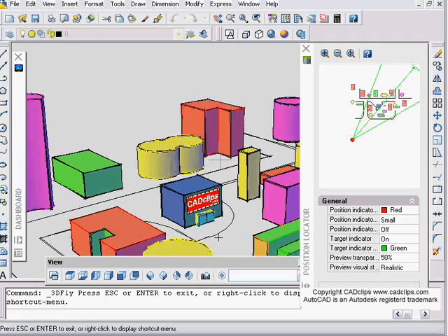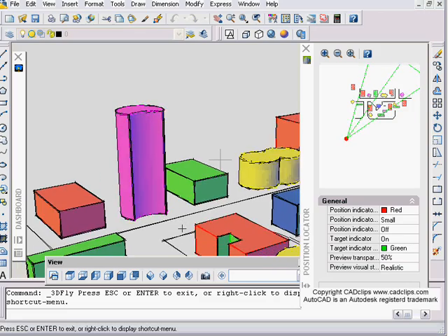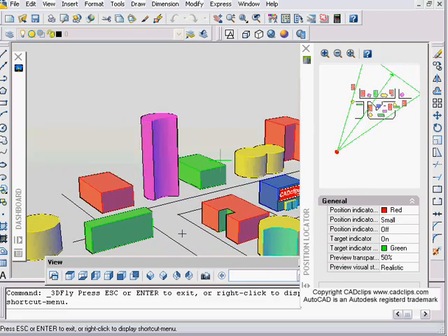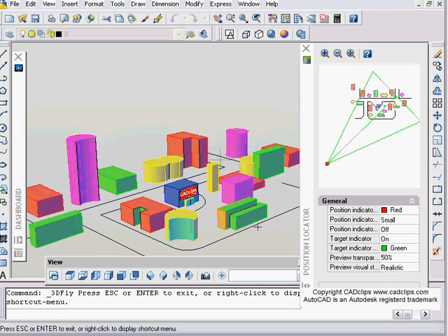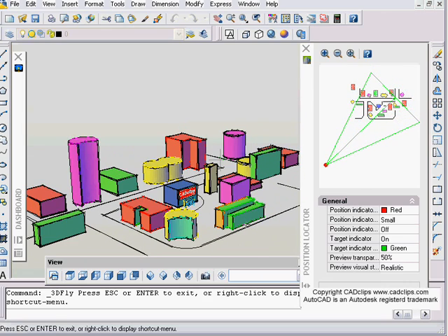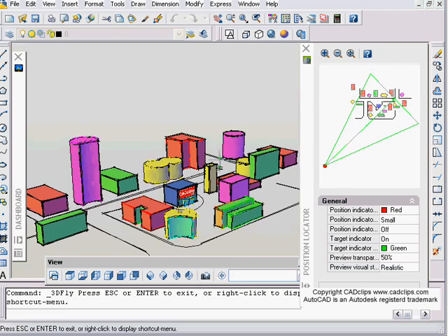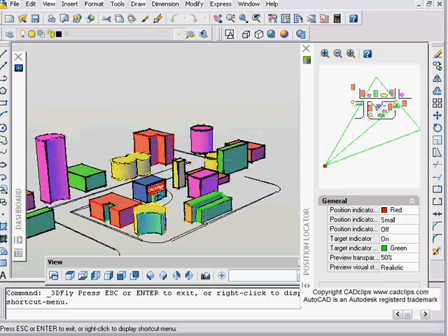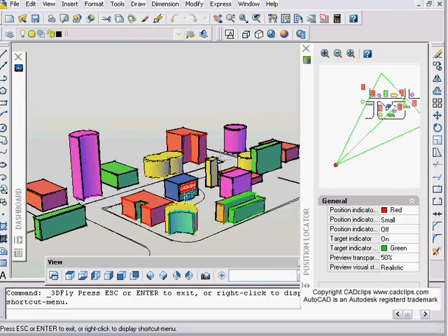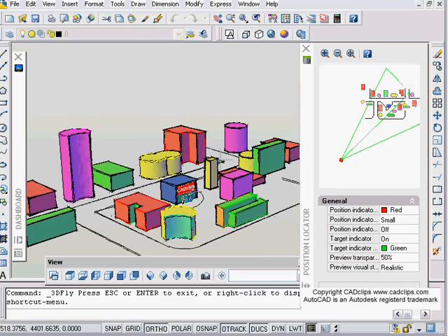okay, and then going down, and then you can fly up, and then maybe we want to use our right mouse button and go over here and maybe back up a little bit as we please. Sometimes it's easier to get yourself in position beforehand. So using your arrow keys, okay, while in here, to go back and forth, and your regular left mouse button to use your eyesight. It's a two-handed operation. And then in the middle of walking and flying, you can actually mouse around with a regular mouse button and wheel in and wheel out. You can't use your shift middle mouse button when you're in a fly mode.